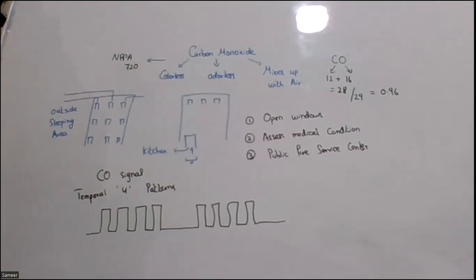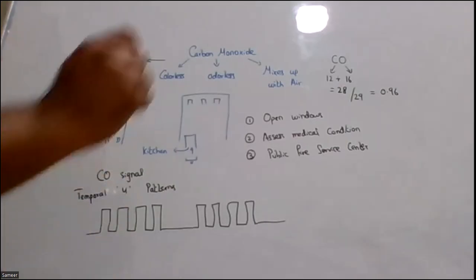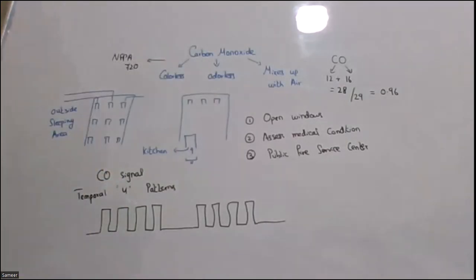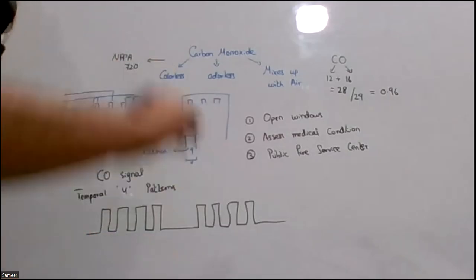So we look throughout the 5 years, because in those 5 years the manufacturer is providing me the warranty that they will provide the components, but that doesn't solve my problem. Why? Because I'm not going to purchase a system for just 5 years. I need to know whether this device is actually reliable for me or not. Maybe I need 25 devices for my next project. So I create a bathtub curve to see the statistical failure during the passage of time, whether it's consistent or whether it's fluctuating higher or lower.